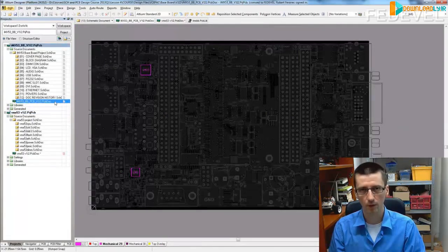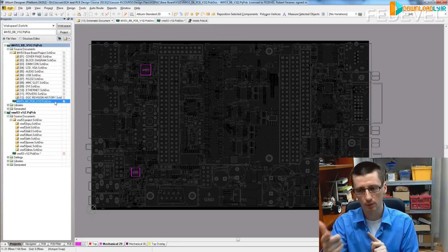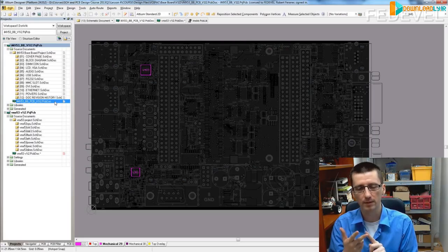So there is a lot of work for this week for everyone who is working on their own project. Create footprints for all your symbols, and add a 3D model for all your components. If you don't have your own project, do it for Wojpak, but you don't have to do it for everything because there are a lot of components.